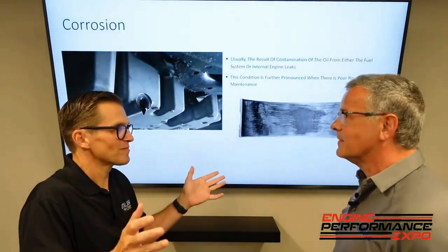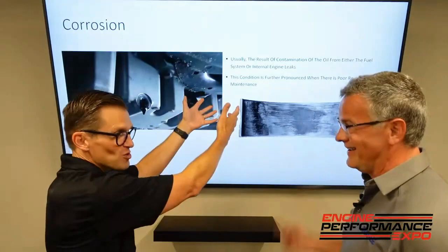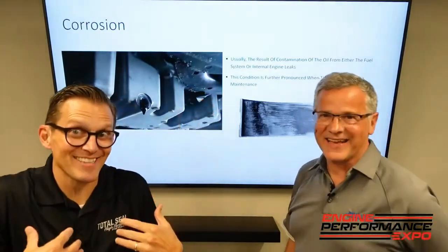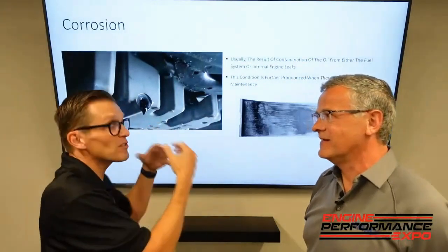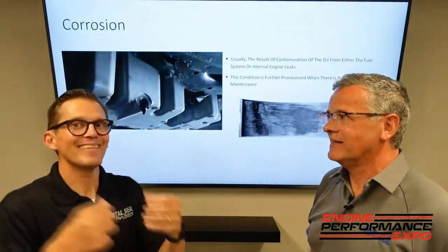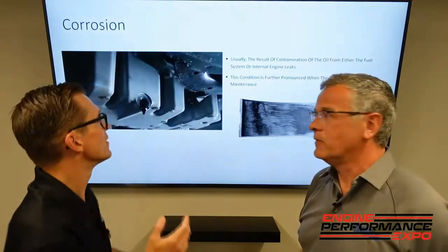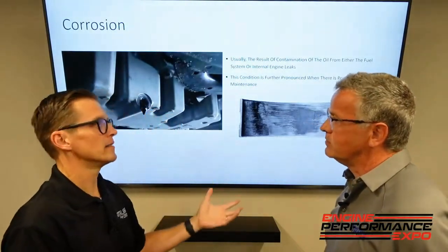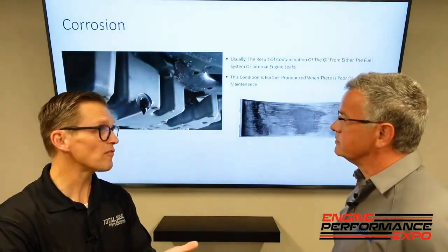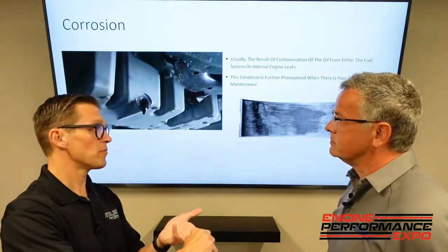What's the difference? Turbines are not exposed to it, right? The piston ring guy's like, hey, we live because there's combustion up here, and it's the contamination of the unburnt fuel in the blow-by that kills the oil. So it's the acids that are created from the fuel itself and from the moisture, right?